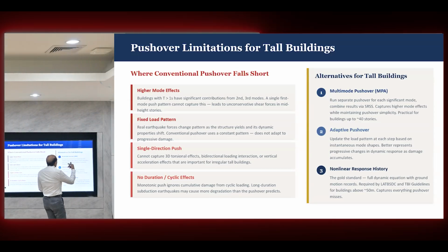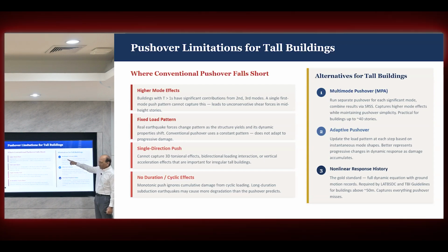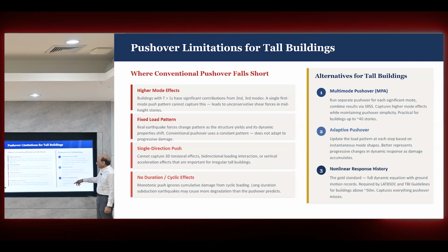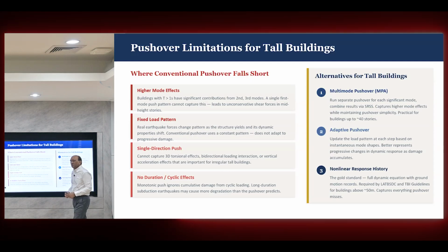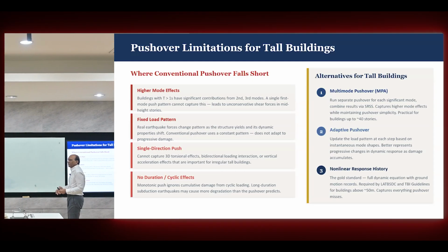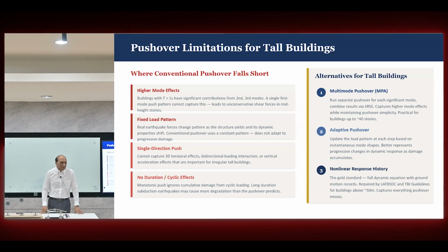So for tall buildings, people use multi-mode pushover. Like I said, many pushover methods were developed to capture one of these problems: higher mode effects captured by multi-mode, adaptive pushover, and nonlinear response history. So we will now go to number 3, the last one, where we don't use pushover, but we use full nonlinear time history analysis, which is the final step in our whole study. All right, so far, all clear?